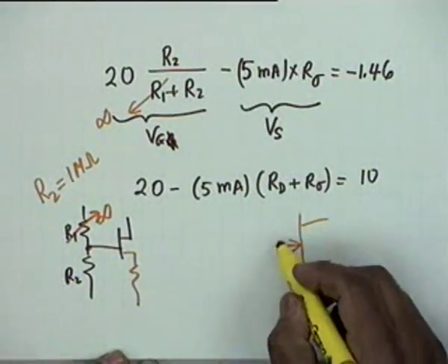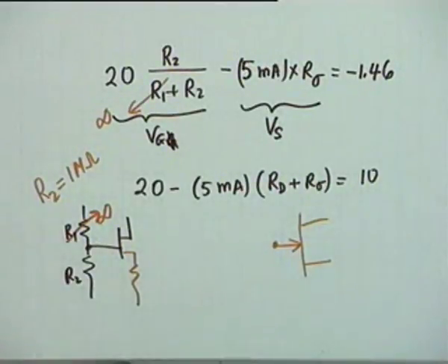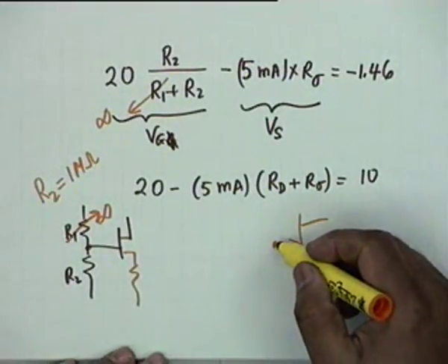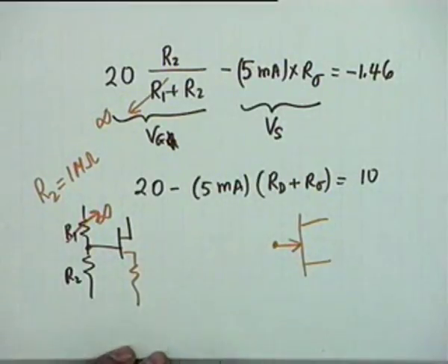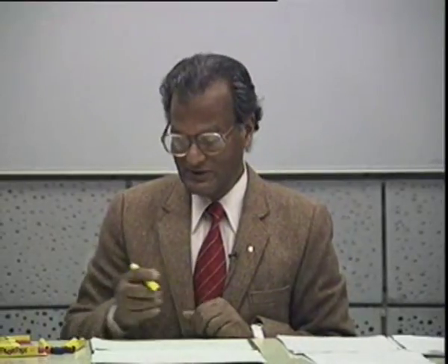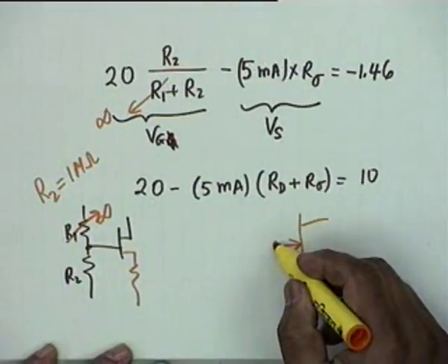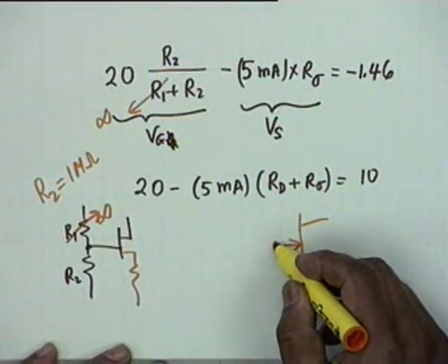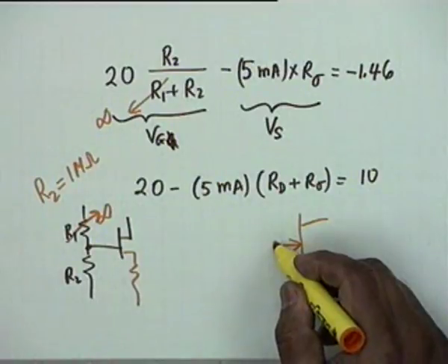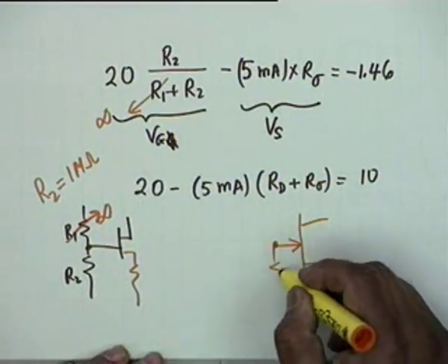The danger is that if this terminal is left floating, it accumulates charge, static charge from the atmosphere. Suppose it is a very dry atmosphere, then there is static charge in the atmosphere. It accumulates charge, and VGS may be such that the operation goes into a different region. Also, then VGS will not be controlled. So what we want is, we must provide a path for any charge that tends to accumulate to go to ground. That's why we must use a resistance.